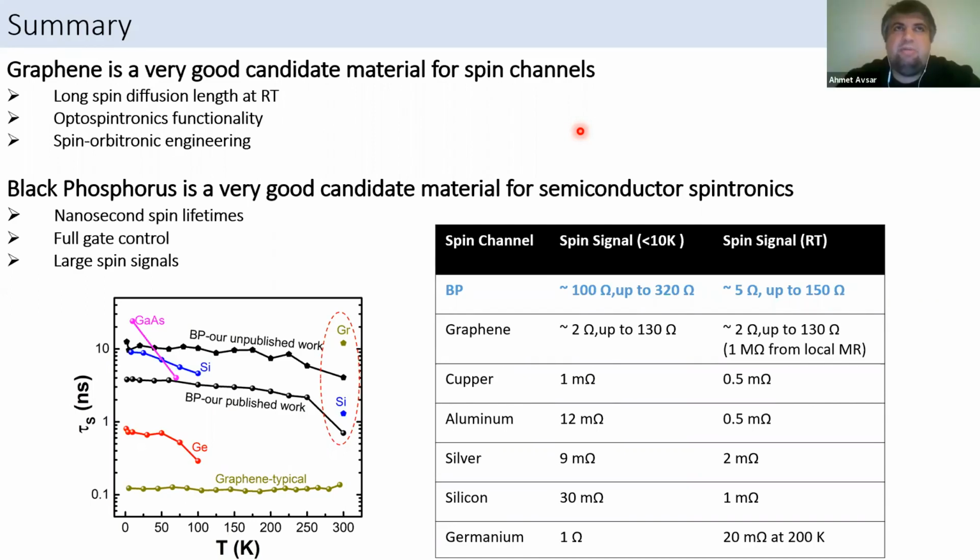No, the problem is you really need to seal the black phosphorus. If you suspend it, then the bottom part still gets some air penetrating, so the bottom part will still be degrading. So the idea is to fully encapsulate it so that there is no air going into your black phosphorus.